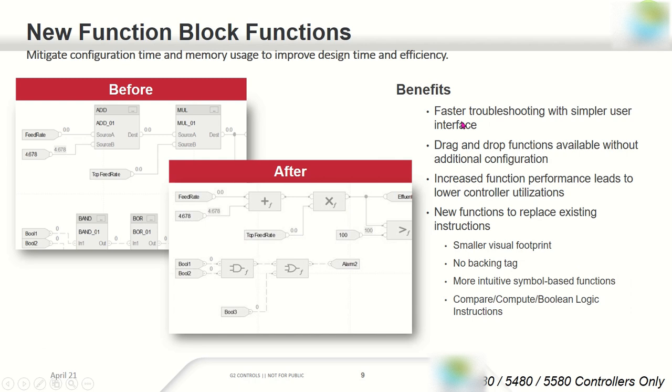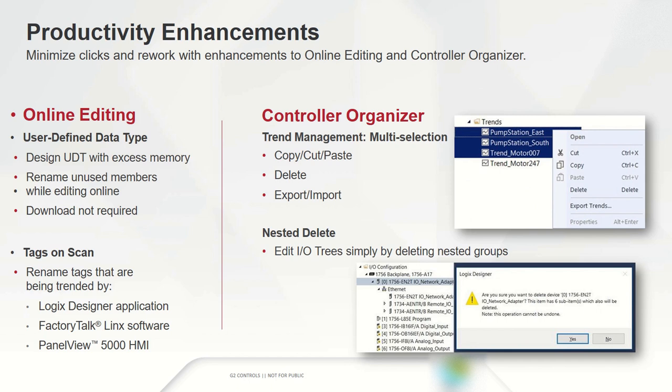The benefits are faster troubleshooting with a simpler user interface, drag and drop functions available without additional configuration, increased function performance leading to lower controller utilization, new functions to replace existing instructions, a smaller visual footprint, no backing tag, and more intuitive and symbol based functions: compare, compute, Boolean logic instructions. We can see that functionality in the lab program.